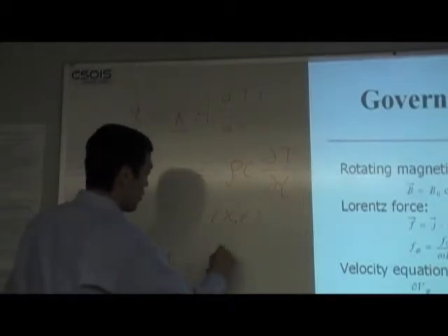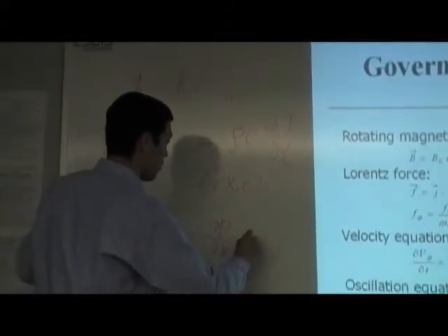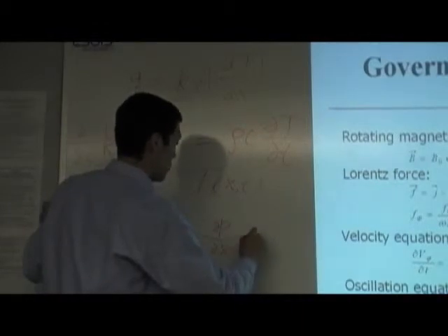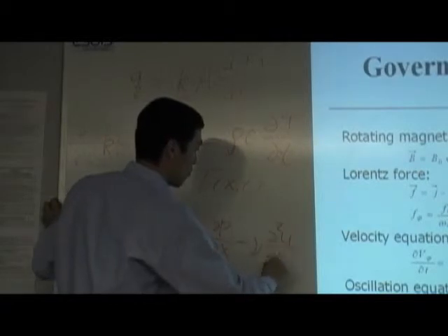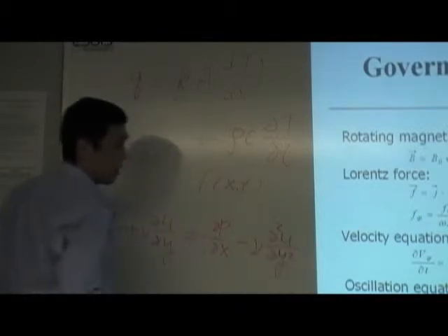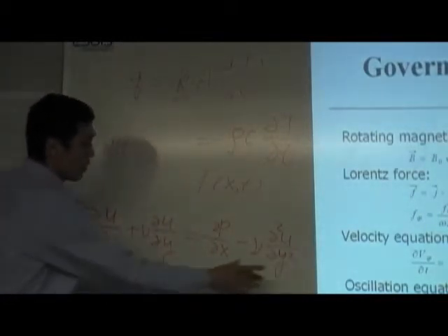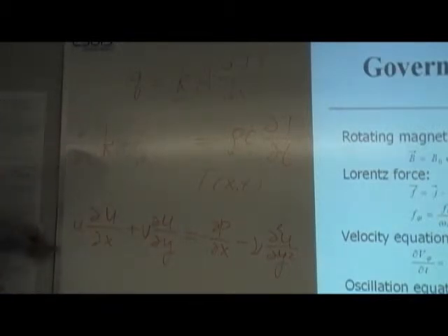So you have a pressure term, the pressure gradient, and the viscous term. Simplified, you can put both of the del squared terms here also. So you have viscosity, so it's nonlinear. U and V are the velocities to be found, so you have equations for both U and V. It can be 3D, and it can be in different coordinate systems. So these are the things that are our starting point.